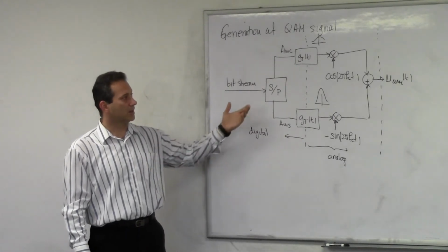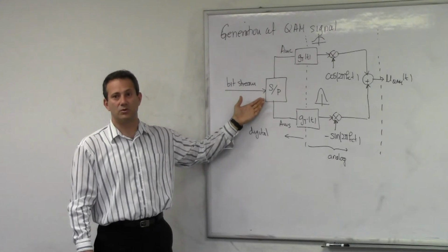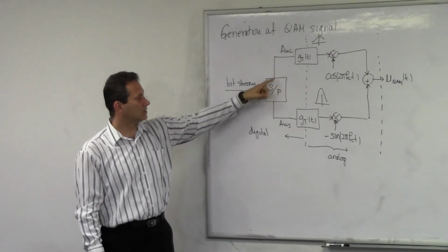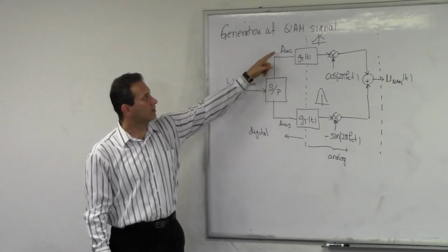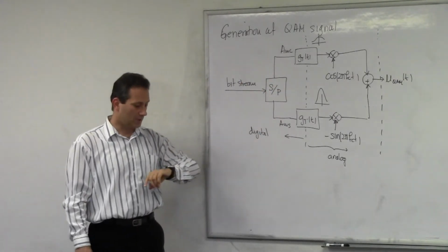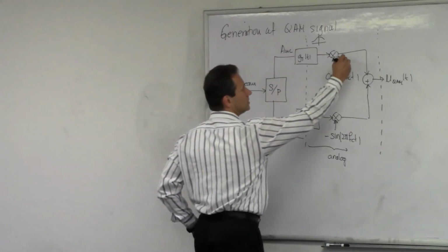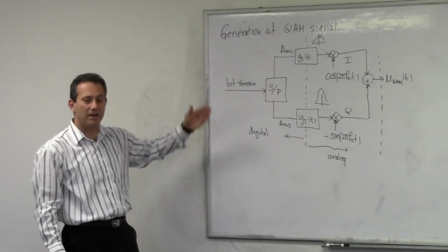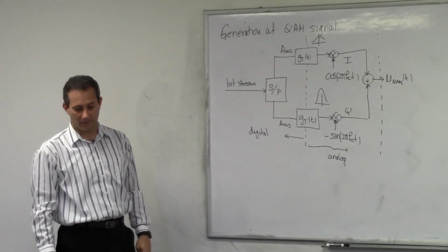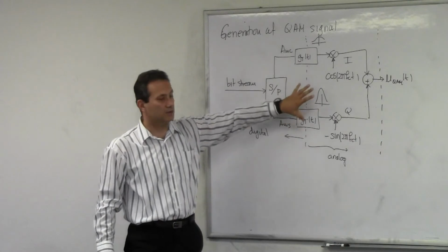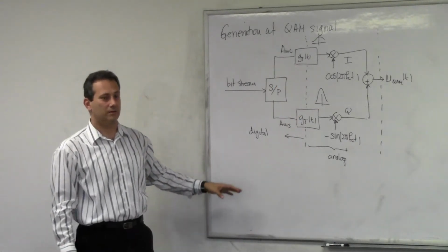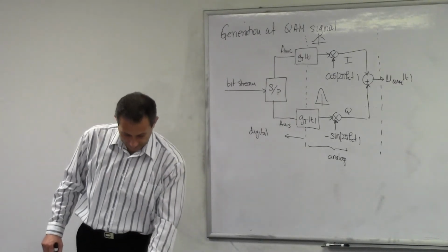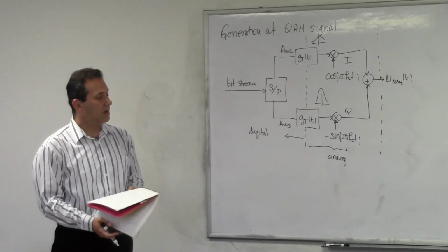These two are very similar. They actually use the same modulator to create the signals. The difference is just that this element here calculates different values that it puts on what we call I and Q branches. This is usually called I, and this one is usually called Q. And this is an I and Q balanced modulator. You can actually buy a circuit that is just this, and that you feed with QAM or QPSK, whatever you want it to be. So this is how we modulate.